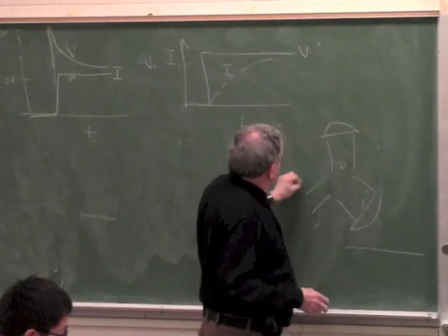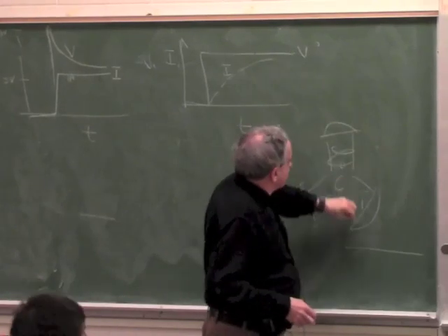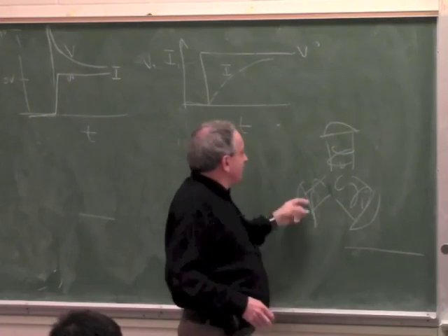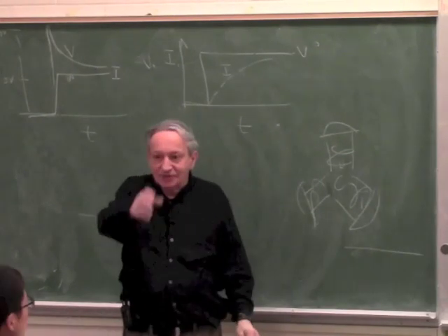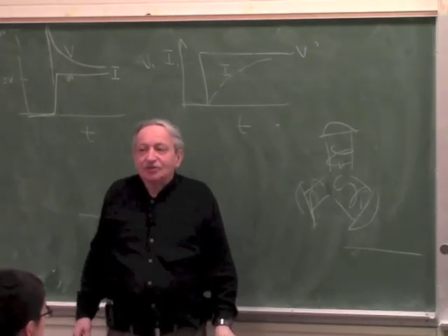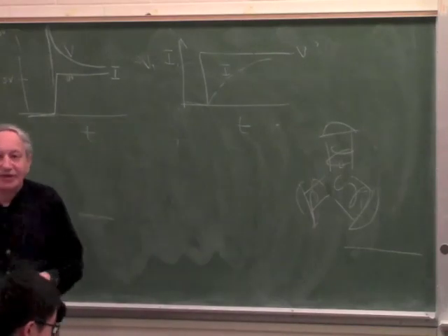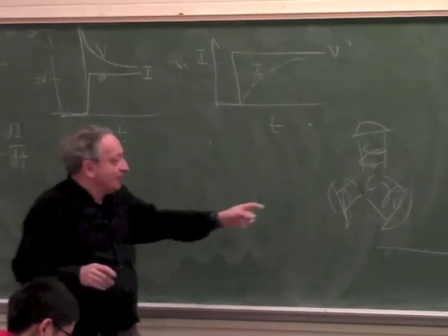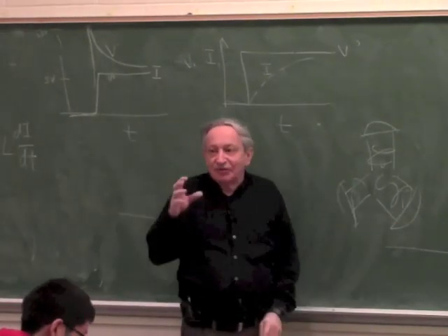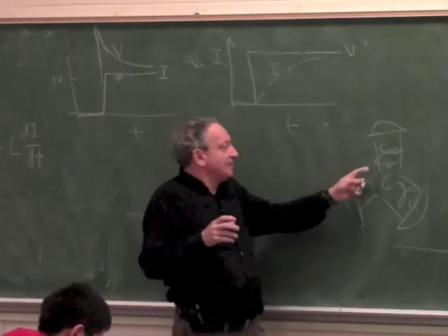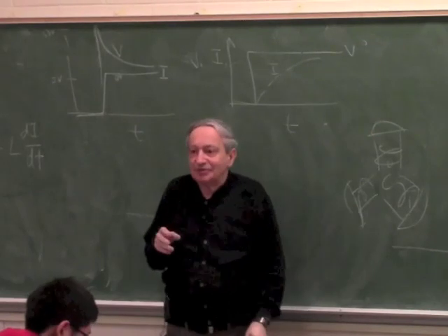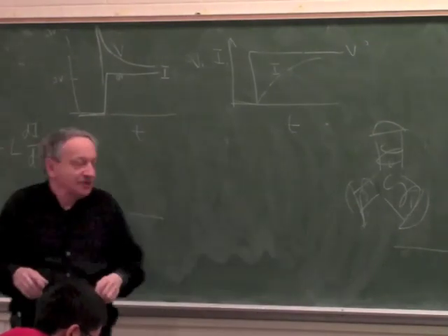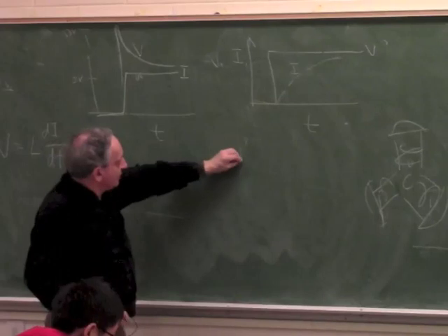The armatures had a piece of steel and then they had coils on it. So they had a lot of inertia because you have to rotate the piece of steel. Okay? So if you take apart very high performance PMDC servo motors, they don't have steel. They only have coils. But if you don't have steel, you can have a big flux because the steel is what helps the flux.